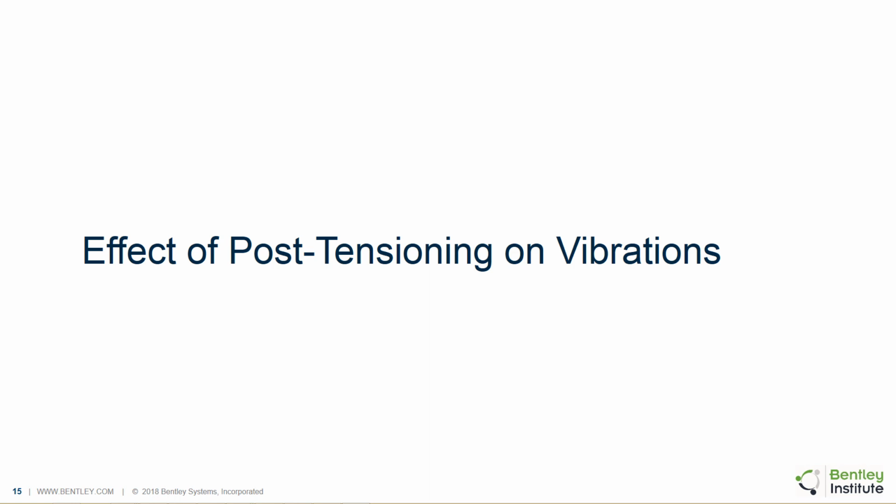I think when we talk about post-tensioning, it's also important to bring cracking into the mix. And some of the research that I've found indicates that cracking is really not that significant in vibrations until the reinforcement starts yielding. So in that case, in most service conditions, the effect of cracking on vibrations would not be that significant. So other researchers, and intuitively you might think, that cracking would reduce the stiffness and thus reduce the frequencies of the modes.